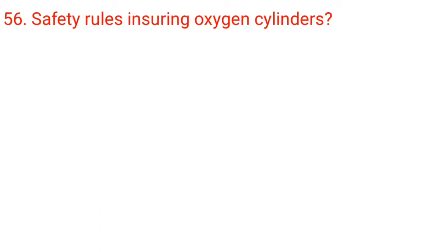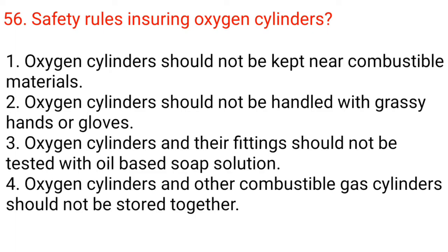56. Safety rules for handling oxygen cylinders. 1. Oxygen cylinders should not be kept near combustible materials. 2. Oxygen cylinders should not be handled with greasy hands or gloves. 3. Oxygen cylinders and their fittings should not be tested with oil-based soap solution. 4.